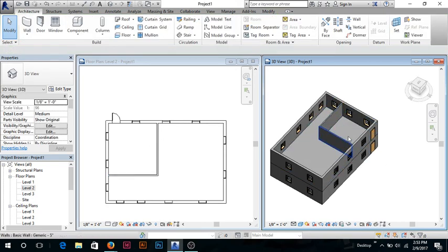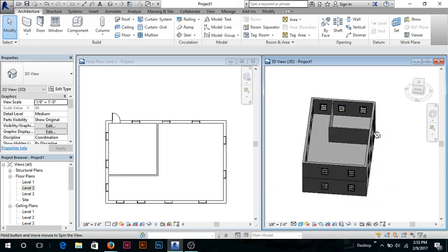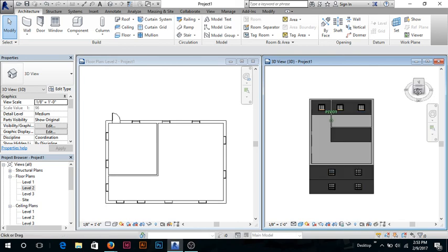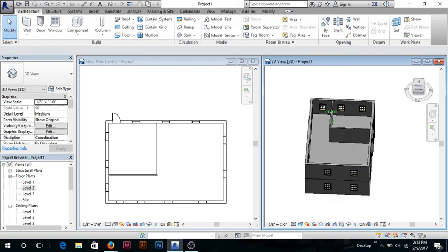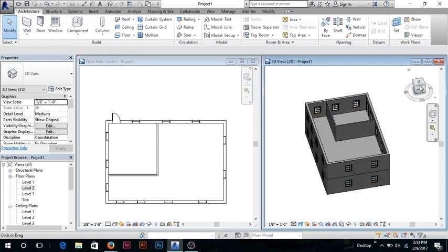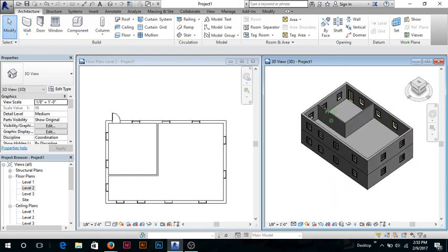Now, if you're having trouble toggling through here, the way I work, I hold the shift button and the center of your mouse, the scroller basically, and I kind of rotate back and forth like this very comfortably. If you're having some trouble with this, I can show you how to do it in person next week, or just simply you can click and drag right here. So you can use your left mouse button, go to your little box thing right here, and just kind of rotate it over here. It's fairly easy.